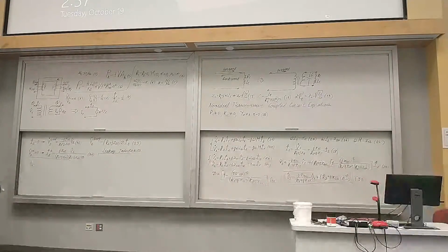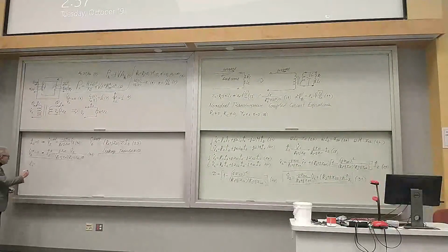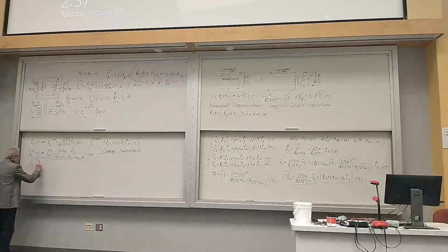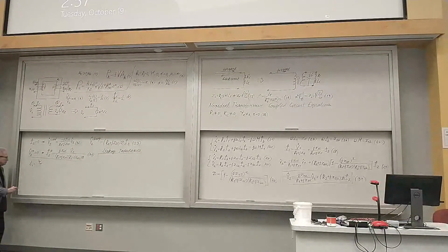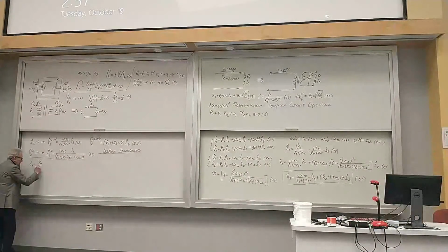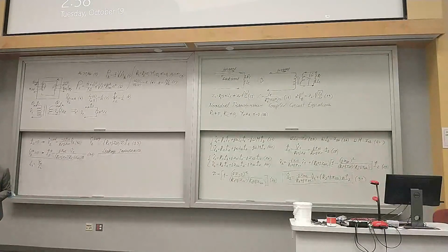This primary current will create magnetic field lines, and they will be coupled to the turns of the primary winding, and they will form what is called flux linkages. They will form flux linkages of the primary winding due to the current through the primary winding. And we will divide by the current, and this will be your inductance.